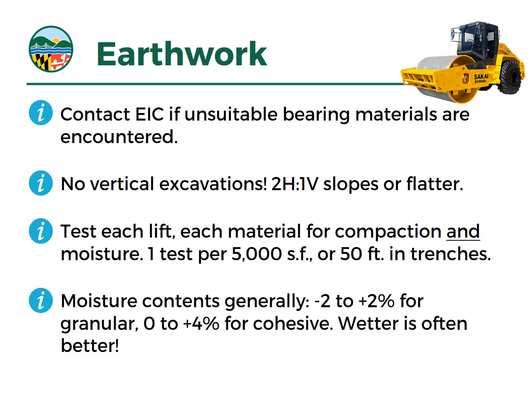If you have to make some kind of an excavation in the dam embankment itself, absolutely would say no vertical excavations. We want 2 horizontal to 1 vertical slopes or flatter. Usually those are some kind of stair-stepped or benches. And what this is going to do is create a good bond between the existing material and whatever will be the backfill in that excavation. We want good binding and to create one single massive embankment again.